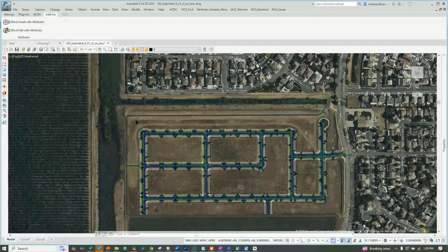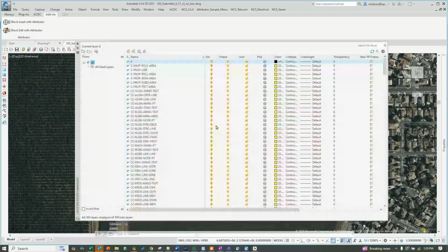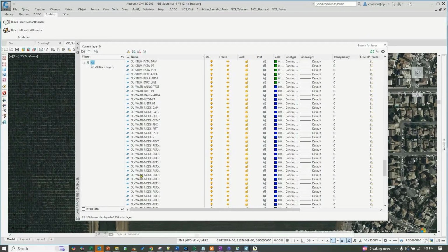Also notice, this drawing that I'm showing you was created from the blank template. The blank template includes all the layers of the off-the-shelf stuff that's supported. You could customize that per project yourself very easily, standard AutoCAD stuff. You may notice this is National CAD Standard naming convention: discipline, major, minor, minor. So you can see a lot of layers for sewer, storm, natural gas. Once again, they are standard regular AutoCAD layers.